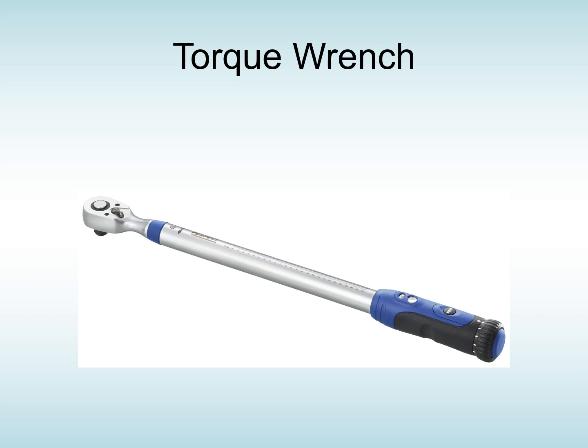Here you can see a torque wrench used for tightening bolts accurately, and there's a good reason why they should be tightened accurately. One thing I would say about these is when you've finished with it, wind it back to zero, because if you leave it with the spring compressed, pretty soon it will lose its calibration.